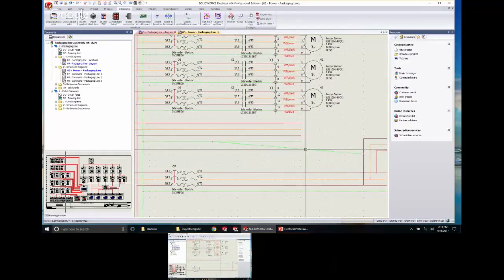Okay, but also if I take this, left click and place it back over that original wire, it goes back to one wire. It's like that rope trick you saw, right, where you keep cutting the rope and then all of a sudden it's one. So that's one of the ways SolidWorks Electrical is not going to let you make a mistake where you have lines on top of lines on top of lines. It's going to either drop it on, or it's going to heal it into one wire.